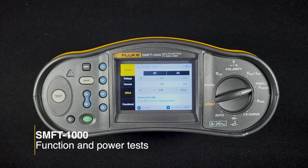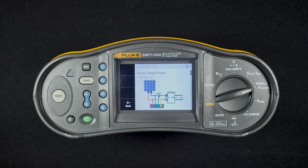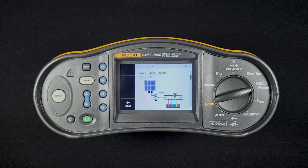We're going to look at the function and power tests in the SMFT-1000. This is the screen you see when you first switch to that test. We have the power measurement here. This is set for a split phase power measurement. What we do is we can go to the info button and see how to set this up. We connect the voltage probes and the current clamp on the DC side. We'll take a measurement there, and then we will move to the AC side and measure the current and voltage there. And the SMFT-1000 will compare the two and give you the inverter efficiency.